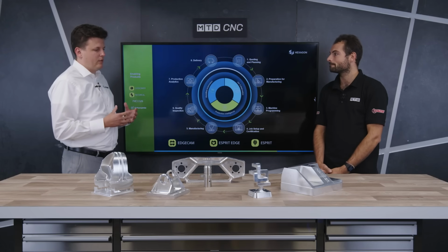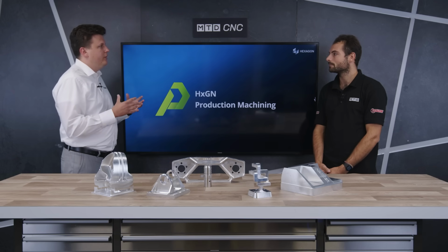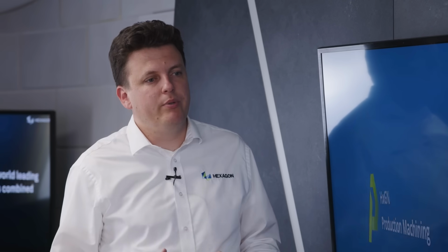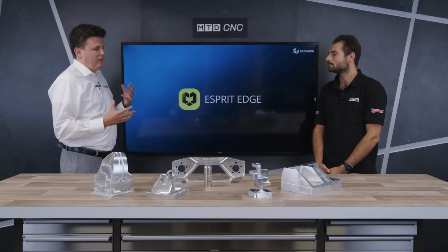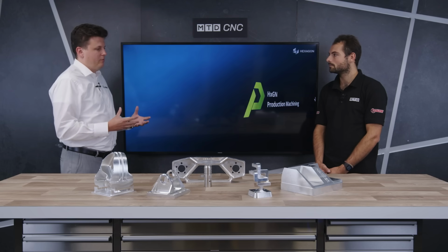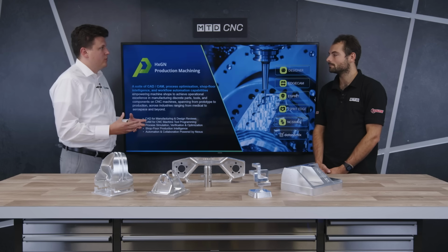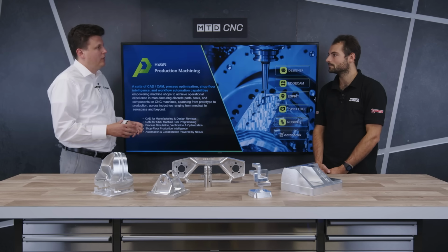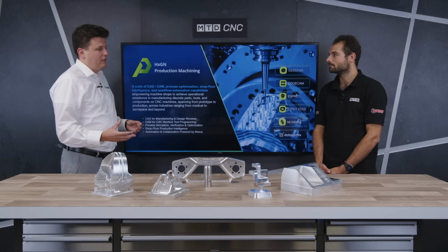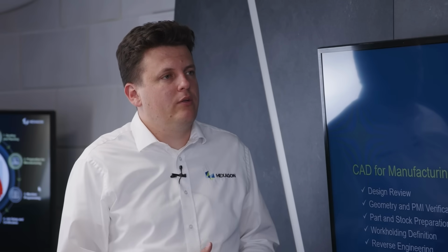Production machining is focusing on the actual discrete part manufacturing. So you could be just a subcontractor, or you could be a company inside an OEM serving your production to be kept alive 24/7. Those customers are getting an order for one sort of part, and they have to get that job done as soon as possible. So they might do a little bit of fixturing, create toolpaths for milling, turning, or wire EDM, and then validate that NC code and run it on the CNC machine. That's what they're trying to focus on.